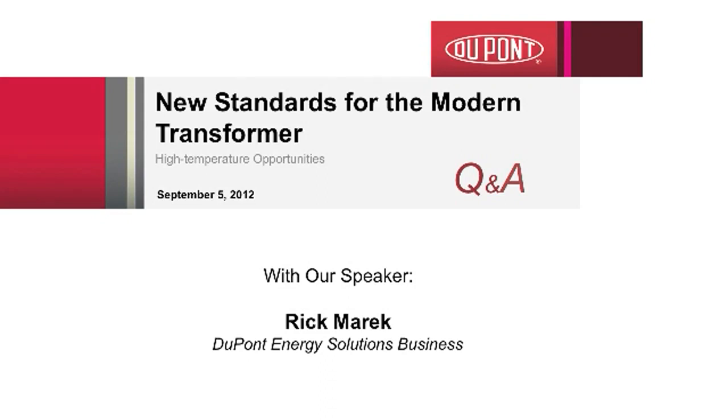But the DGA analysis would remain very much the same, especially in a hybrid type transformer. In looking at the high temperature transformers, though, you have a completely different set of materials, and likely an ester or a silicone, and guidelines have not been developed yet for this type of application. Thank you, Rick. Here's one for you.